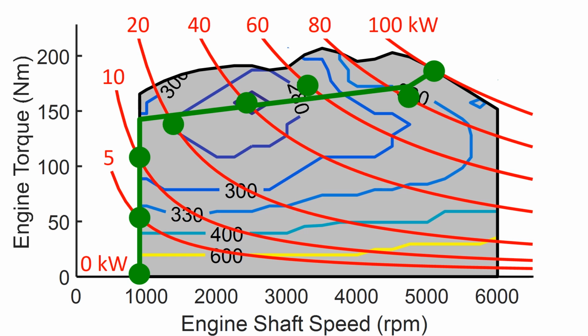We can see a trend for what is the ideal operating point as the required engine power varies. At low power, the minimum speed is the most fuel-efficient choice, and when the power is higher than about 15 kilowatt for this engine, the most fuel-efficient operating point is at a high shaft torque, a little lower than the peak torque of the engine. The optimum operating points at higher powers are not exactly the same engine torque, but they vary a little up and down depending on details in the fuel consumption map of the engine.